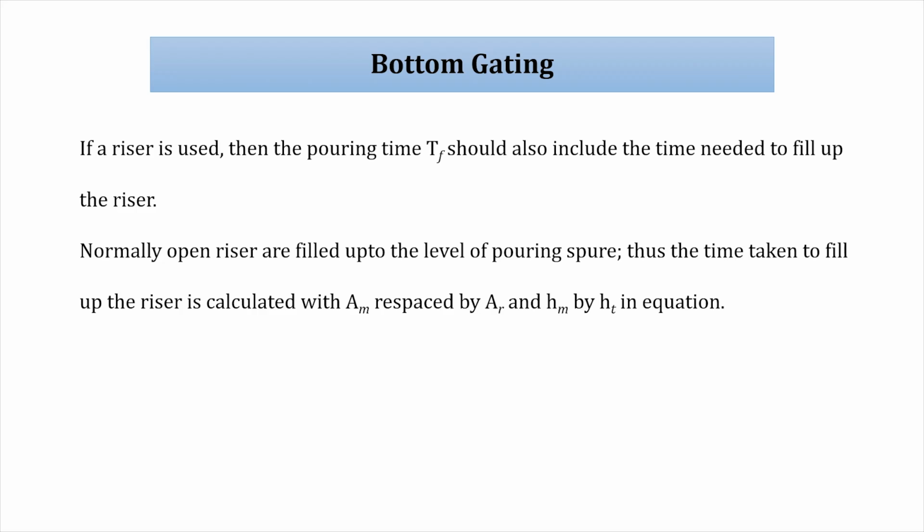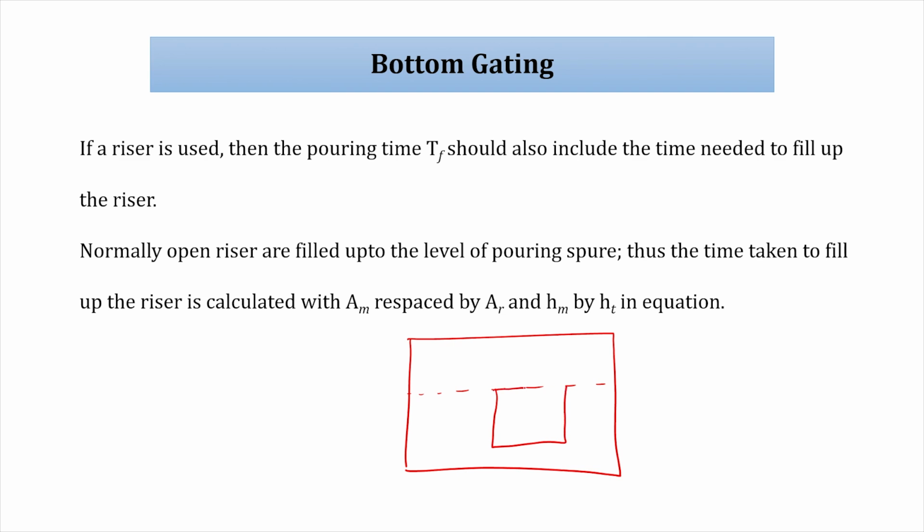Now there is some calculation you can change. If a riser is used, let us assume this is the casting and this is the riser, and you want to fill this mold cavity from the bottom gating or even top gating. If a riser is used, the pouring time TF should also include the time needed to fill up the riser.